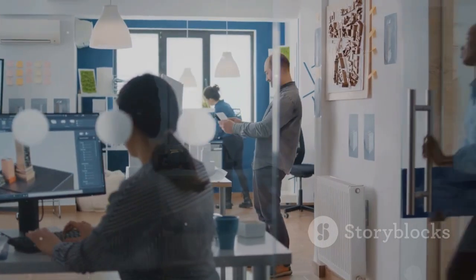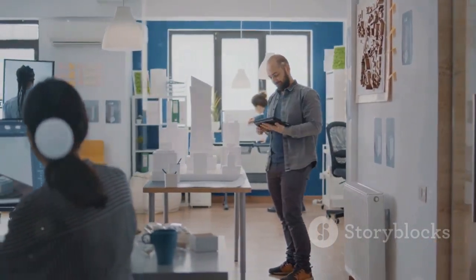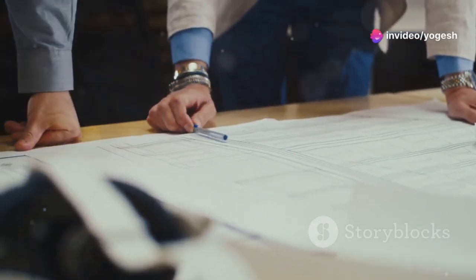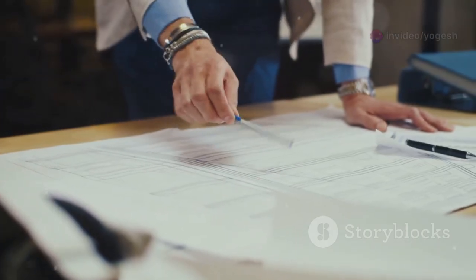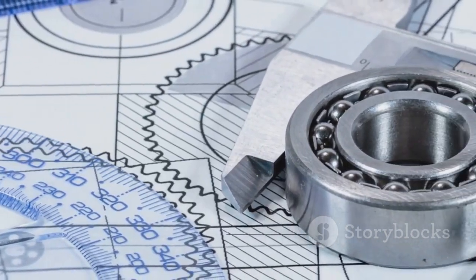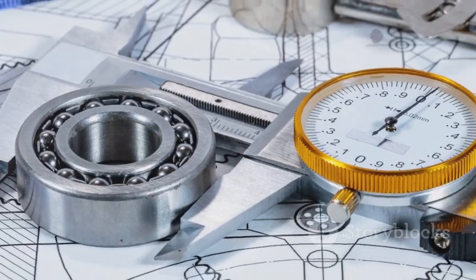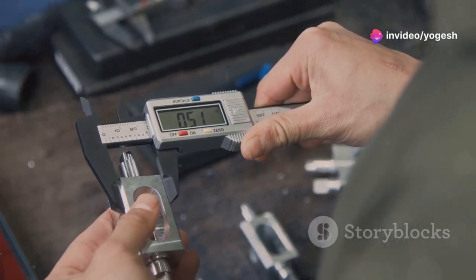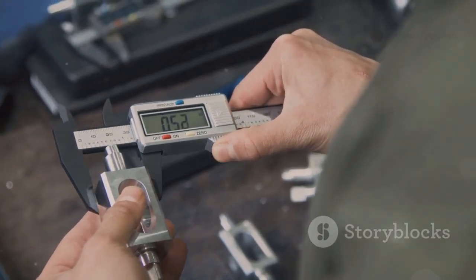In engineering, we use an imaginary cutting plane. Think of it as an invisible knife to reveal the internal geometry of a part or assembly. This allows us to look inside complex objects without actually destroying them. By exposing these hidden features, sectional views turn invisible details into something you can measure, analyze, and discuss directly. This is crucial for manufacturing, quality control, and troubleshooting.